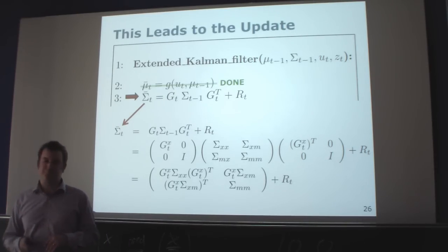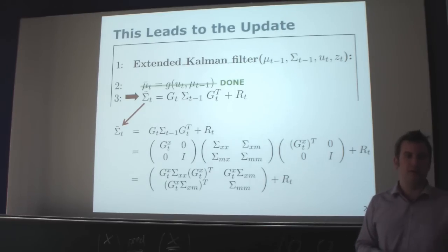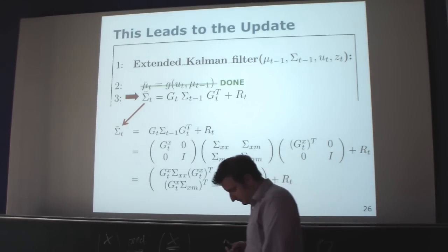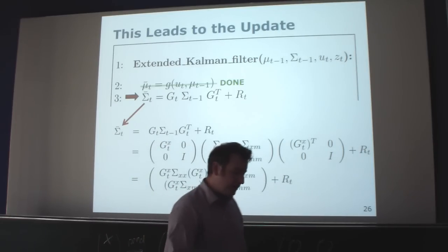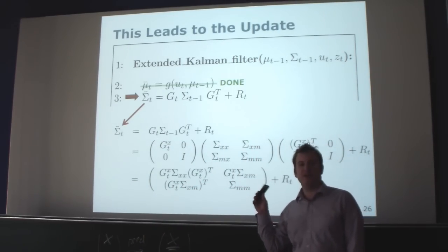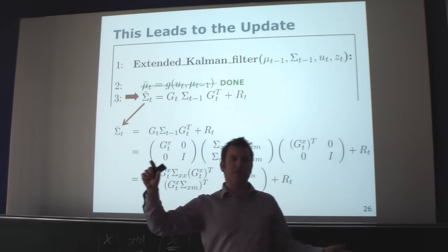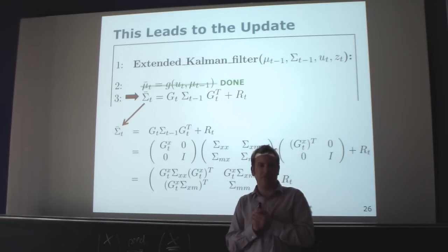Okay? There's no question about this. Sure. RT. In the motion model, when we just want to plot the uncertainty, we end up with a banana shape, because we have many uncertainties. But here, look, we have only one. Exactly. So the thing is, in the models I presented here, I showed that kind of banana-shaped distribution which results from executing these motion commands, is the distribution you obtain if you really conduct those steps.